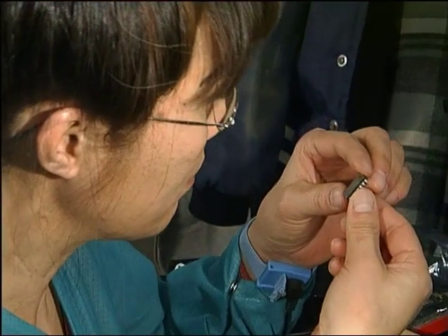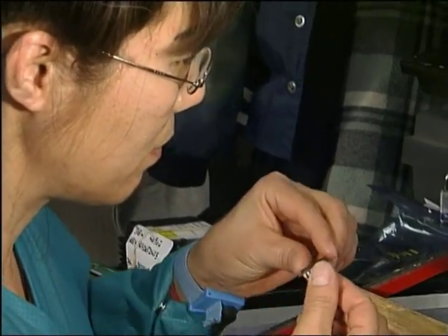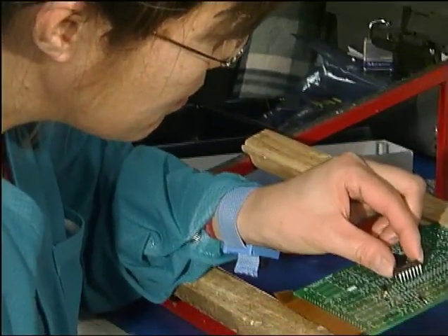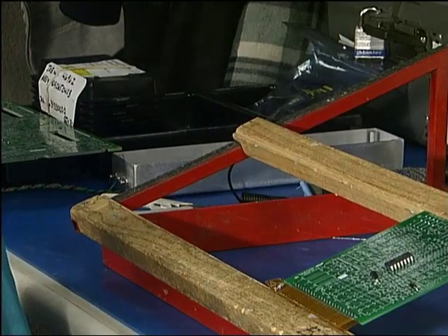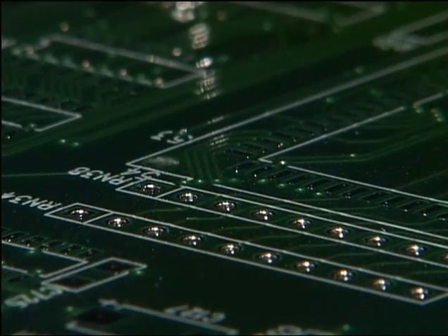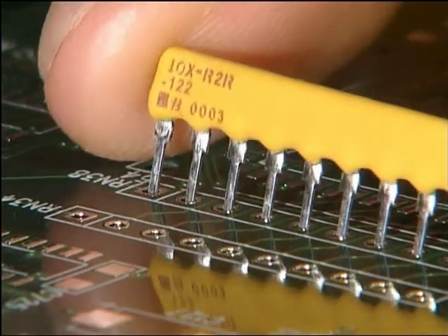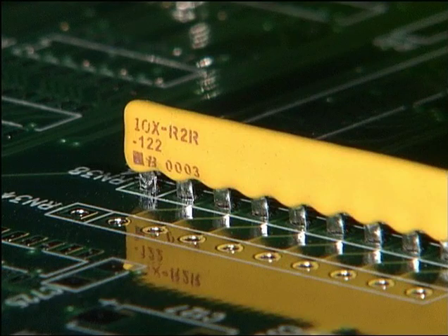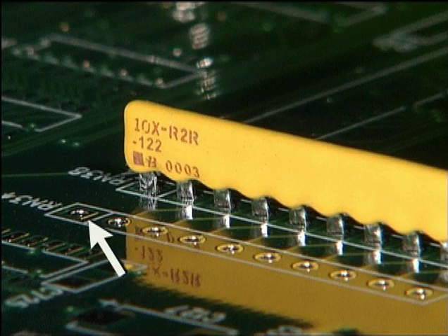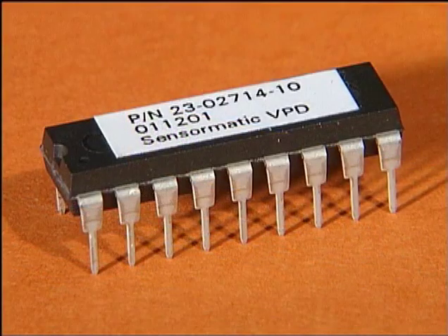The direction in which a component is installed is also important for components with multiple leads, even if they do not have polarity. Proper orientation means that pin 1 of the component is in the same position as the pin 1 hole on the circuit board. The board usually has a square pad or a symbol or screened outline of the component shape to show the correct orientation. IC manufacturers use a variety of methods to identify pin 1 on the component package.